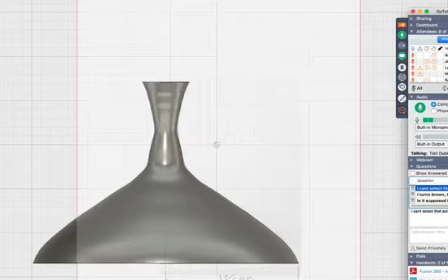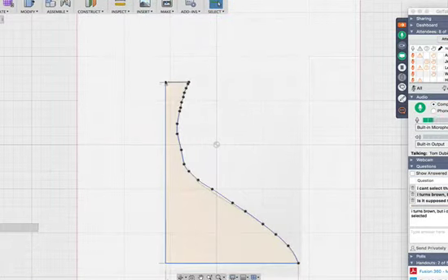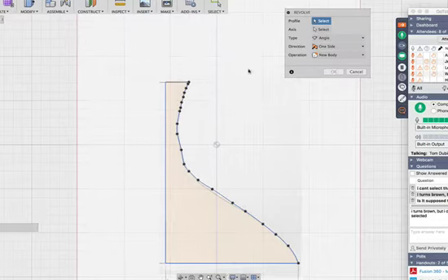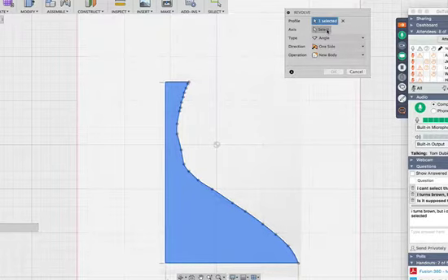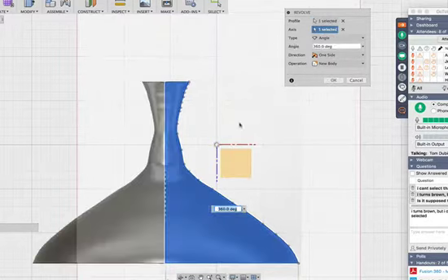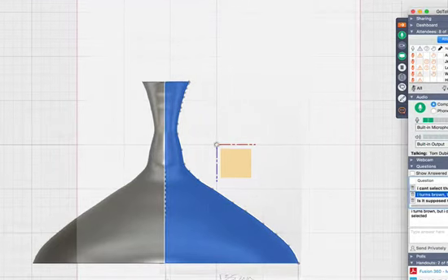Turns brown, but I have the axis above. Okay, no, here, let me show you what you might not be doing, Philip. Watch me, man. I've got it here. I go to create. I'm going to hit revolve. I'm going to go up to select the profile. You select. Go up and where it says axis, click it, make that blue. Then hit select. Okay?